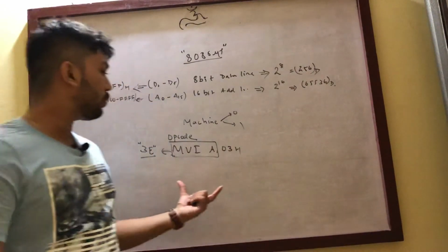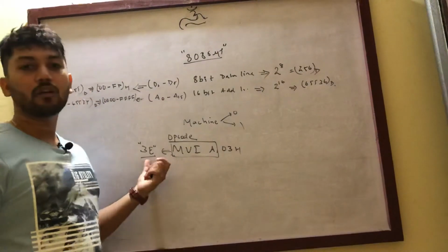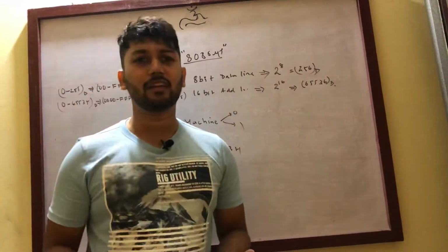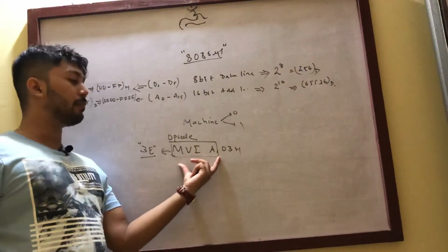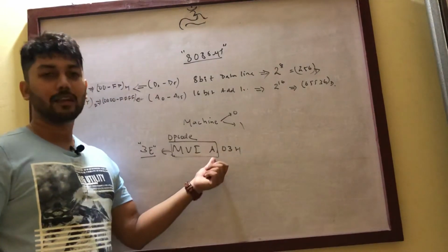So you just need to understand what the MVI A instruction does, and the opcode will be given in the 8085 microprocessor kit. Mostly in the kit, only the picture has been put up, so you don't have to memorize it. But what does it mean? MVI A is move immediate data to register A.